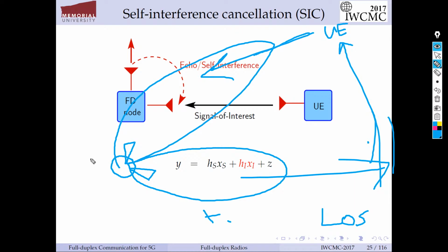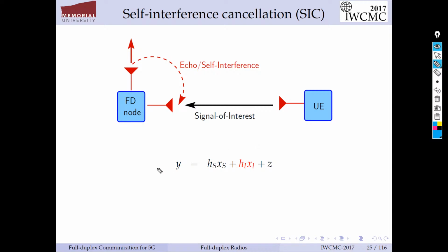Now you can consider the transmitter in full duplex, the receiver in full duplex, or both of them. Another example that can help you mitigate this interference issue is what if you can utilize the millimeter wave capabilities? You have your transmitter here and you have your receiver. We said in millimeter wave, the polarization is not rich. For example, if you send a signal with vertical polarization, you receive it with vertical polarization.